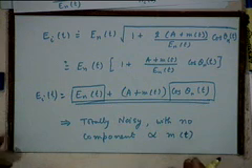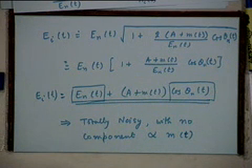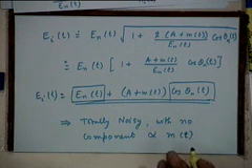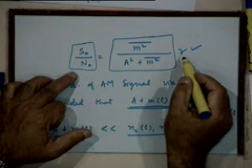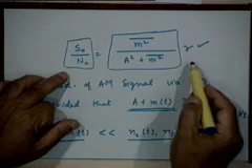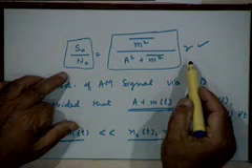Right. So what does it mean? That means under large noise conditions, the envelope detector fails to deliver a signal of interest. It completely breaks down. Right. Now, how does that compare with what the synchronous detector would have done at low SNR, in the large noise conditions? When we derived this expression for the case of the synchronous detector, we did not have to make any assumption whether the signal is small or large. This expression was valid for all conditions of signal and noise. Right?